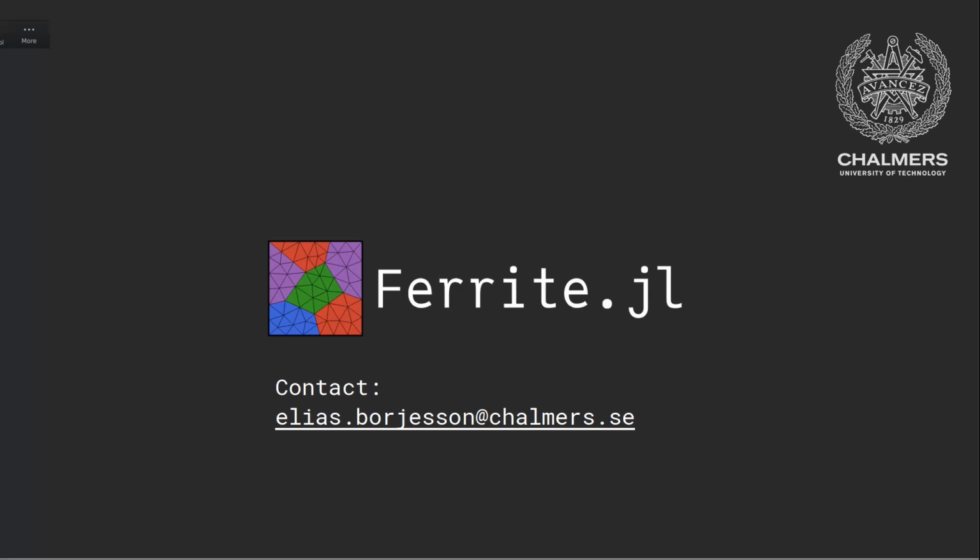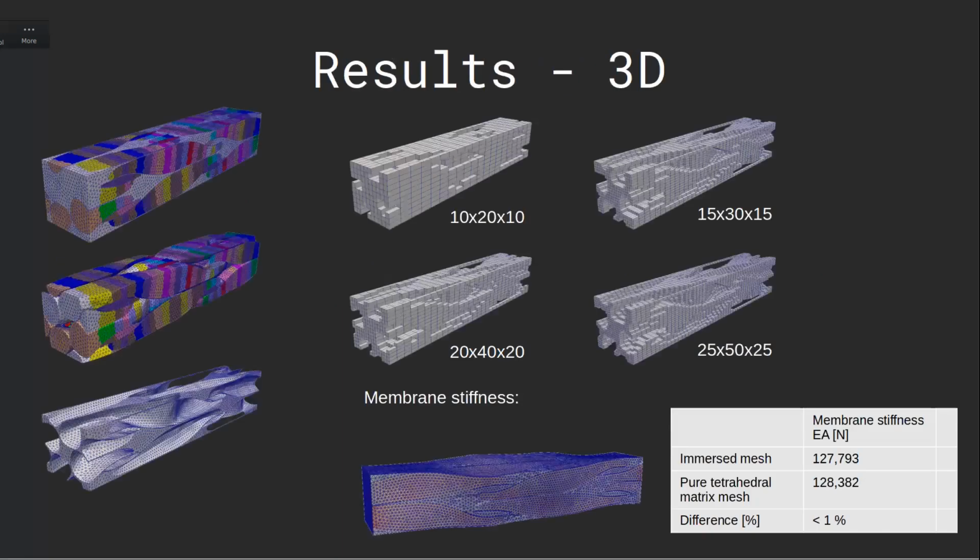Christopher? Yeah, I have a few questions. The visualization grid, isn't that hard? The point is it's hard to mesh the thing to respect the boundaries. How can you do the visualization grid that has to respect the boundary? No, so you don't have any requirements on the elements there. You don't have any requirements on the quality parameters basically, and you don't need maybe the interior elements, maybe just the surface mesh, and that's just 2D. So I think you don't have the same requirements for that mesh.